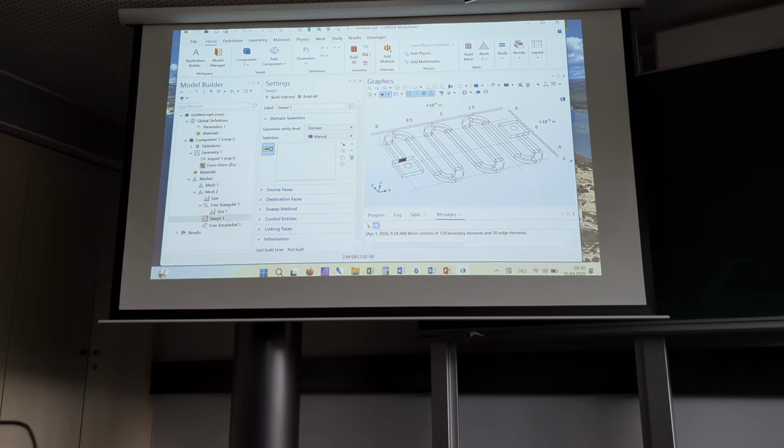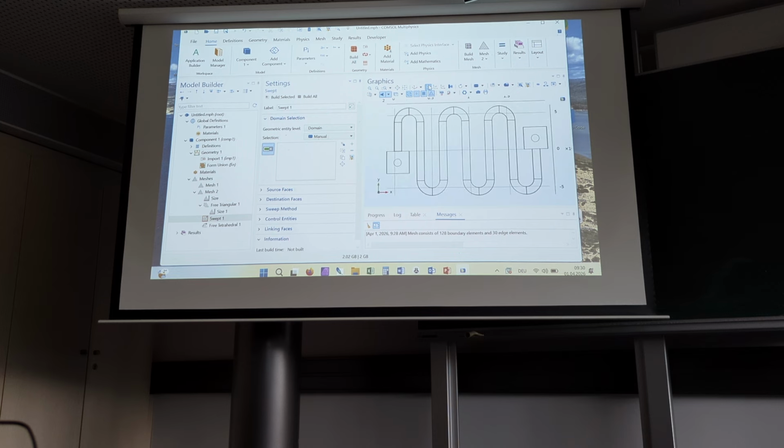Now, like I said, you could click all the things, and here it would be possible. Sometimes it's useful to change the view for selection. Maybe we go to XY, then we have a top view, and then there is a selection feature called select box.